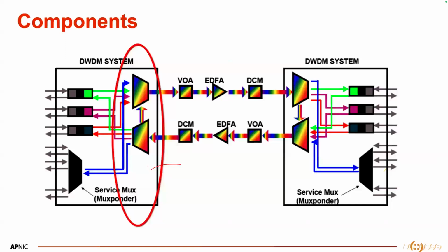We are not going with multimode because multimode fibers cannot actually take your signal to tens of kilometers or 20 kilometers or any bigger value. If you use multimode fiber, you will need to use a regenerator node after every 2 kilometers or 3 kilometers or something like that.